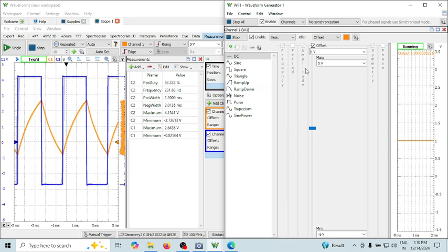What will change when you change this reference voltage is the on time and the off time, and the capacitor voltage, that is VTH and VTL, will change. So let me go back to the equation and show what all things will change.